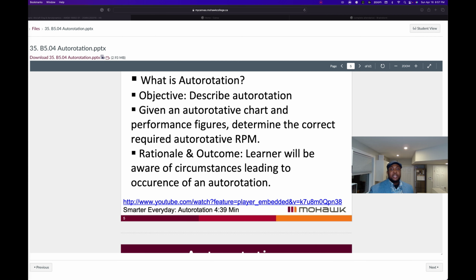The shaded area on the right is also a no operation zone. The danger of operating in this area is insufficient time for auto rotation due to close proximity to the ground. Over here, yes, you have enough airspeed. If you were anywhere in this area, operation would be safe and continuous operation is advised. But if you are so close to the ground, even with sufficient airspeed, there is not enough time for you to respond.